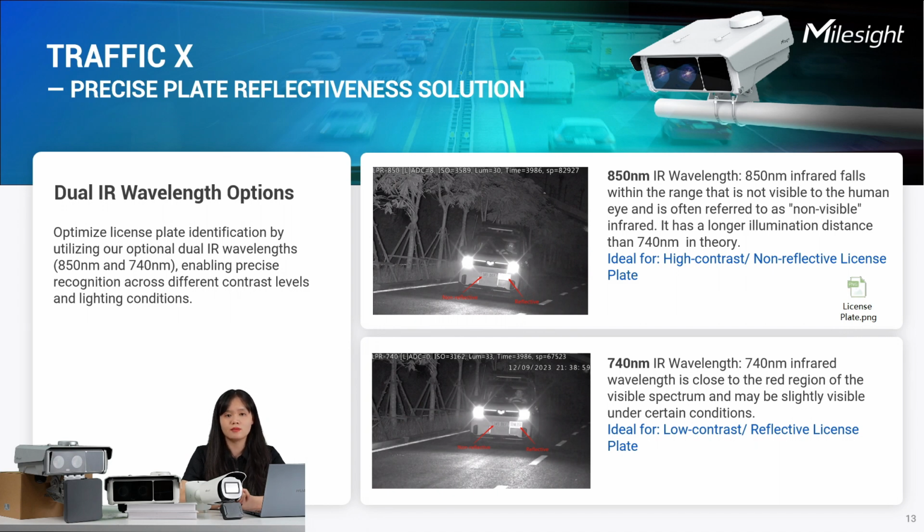Like if your plate is slick or very shiny, the plate may become an overexposed image when the camera uses the IR light for supplement light. But if your license plate is a matte one, it may not be that reflective to the camera's IR lights, and then the camera will not overexpose the license plate.